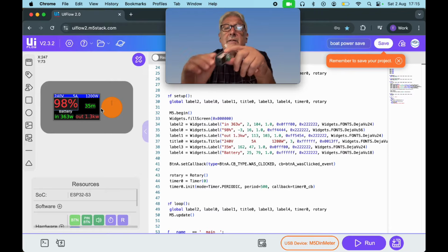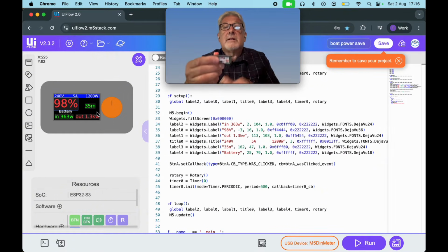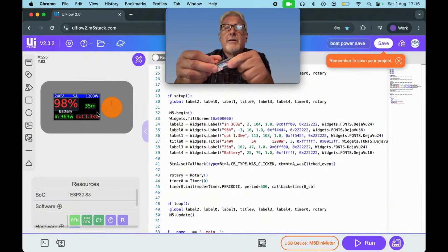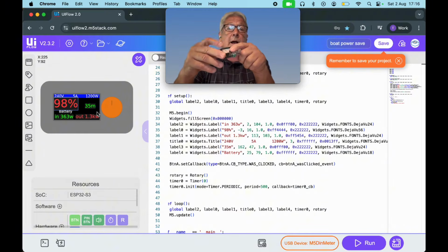So I can say, if you turn this on, and if you turn two of them on, it will do the longest countdown. It won't just turn it off halfway through someone's use. And I'm going to have probably 3 or 4 of these around the boat wherever I use mains power, so that you can see exactly what you're doing. And if you want to use mains power, you have to turn this knob to get it for a certain amount of time. You can also press on off, which will give you like 10 minutes of power.